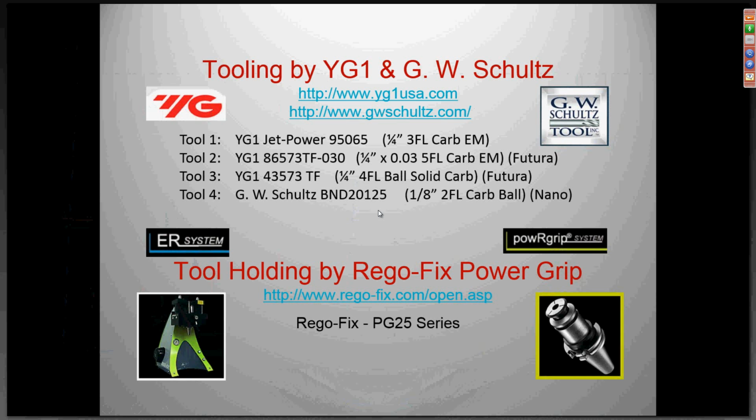We've got a new parabolic ejection cavity tool that we designed that ISCAR is grinding for us. I've done some testing on that where I've run a 10 millimeter tool at 14,000 RPM and 512 inches a minute in steel at 750 thousandths deep at a 60 degree cutting angle. It's just absolutely phenomenal to watch it cut. But I'll tell you what, the down forces on those tools at that aggressive a rate is unbelievable.